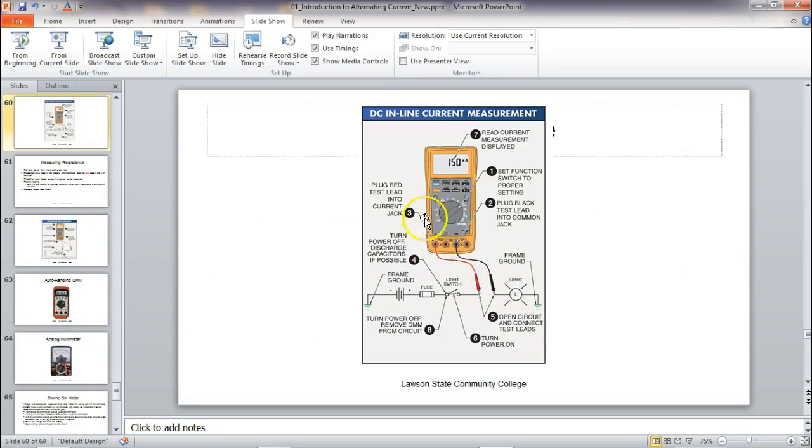So this is how a true ammeter works. You have to make the current flow through the meter. Now, what you have to understand is that since it flows through the meter, the meter has almost 0 ohms of resistance between the common and the amp scale. That means if you put this across anything, you are going to create a short circuit, which is very dangerous. So this is why the amp scales on your meters are fused. Don't ever put a bigger fuse size in there, and don't ever override that fuse.